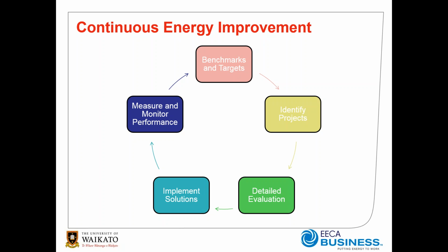Then there's also other methods of doing it, such as process flow diagram reviews and plant walkthroughs. Some of these achieve lower levels of energy savings. They're a little bit tougher to apply to every project or every process. So we're going to focus mainly on the pinch analysis tool of doing targets for your process.